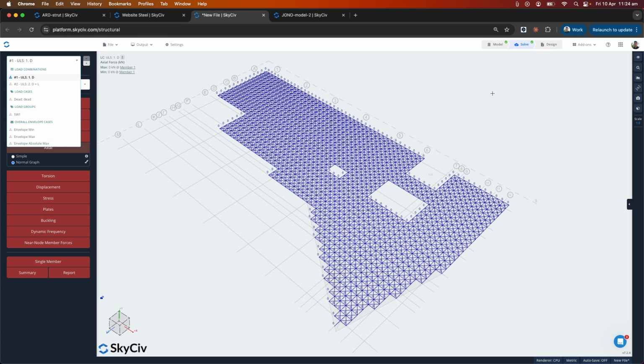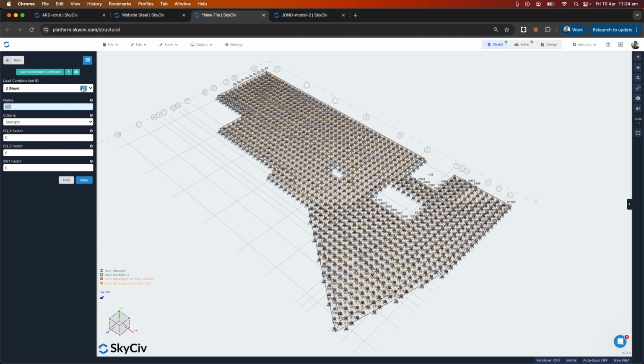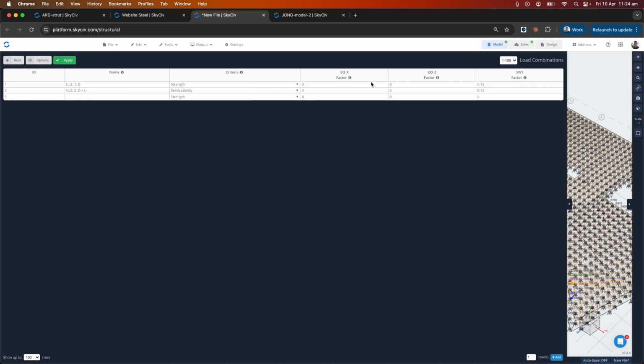One thing I did forget to do, actually, I'm just going to, maybe I can look at my load combinations. I didn't specify a load combination for the EQ and EX. So I'm just going to turn both of them on. I'll leave self-weight on. So I just had to turn on the EQ and then we can just control that EQX.